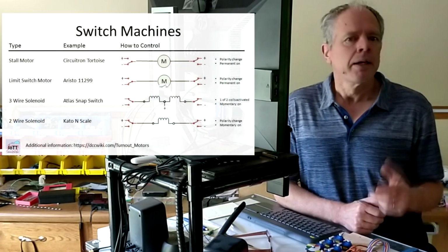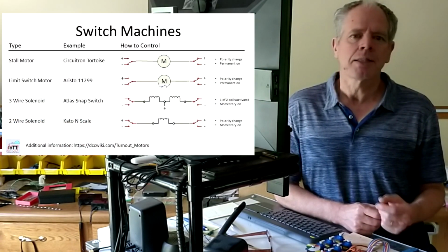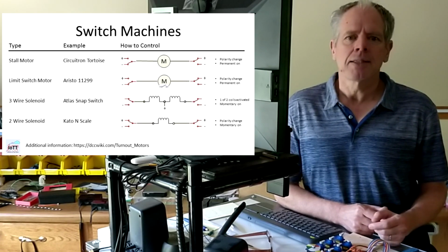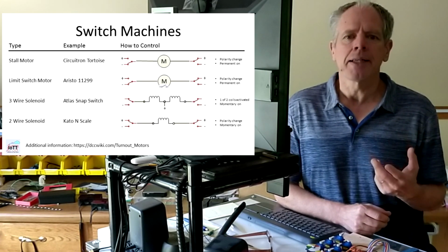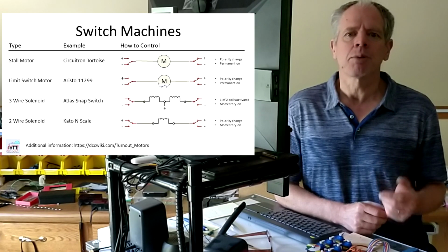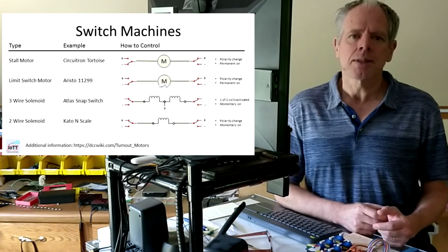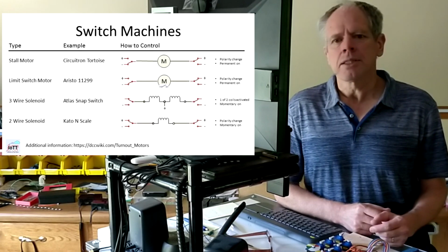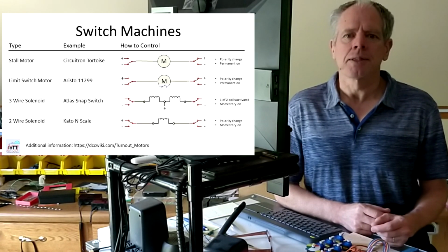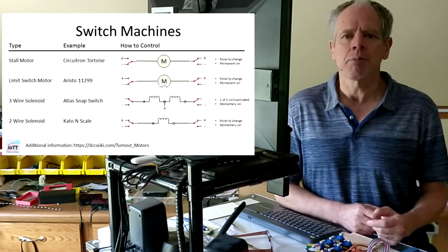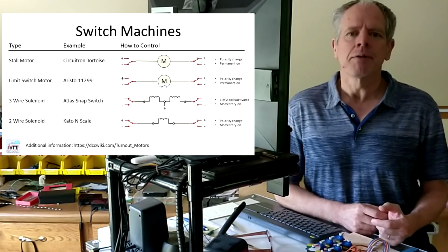To understand the requirements, let's have a look at what we are going to control. Typical devices are motorized switch machines and such with magnets. Motorized devices have a DC motor with polarity selected based on the desired position. It then runs to the end of the mechanical course and either stalls or is switched off by limiter switches. In either case, we can use two relays to supply the required polarity and then leave it with that.